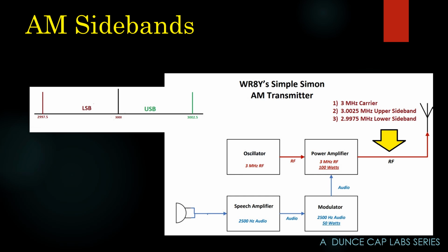If you key the transmitter with no audio, you only have the carrier wave. As soon as you add audio, you get these outer 2 signals. They are literally thought of, and can be thought of because they are, separate signals. That means if we can generate them independently, perhaps we could only send one sideband at a time without the other sideband and without the carrier, which of course we can do. We call that single sideband. But how do we do that?